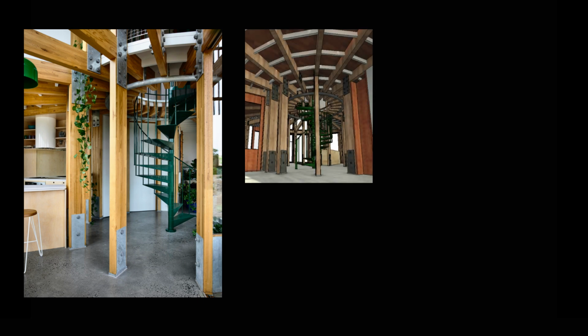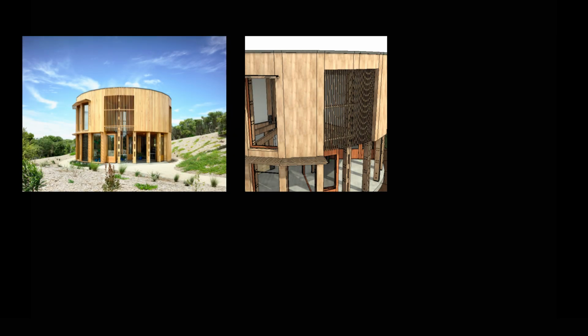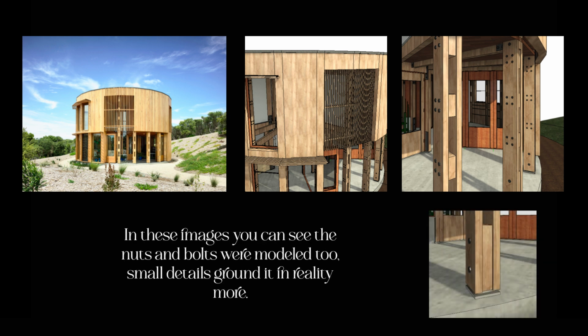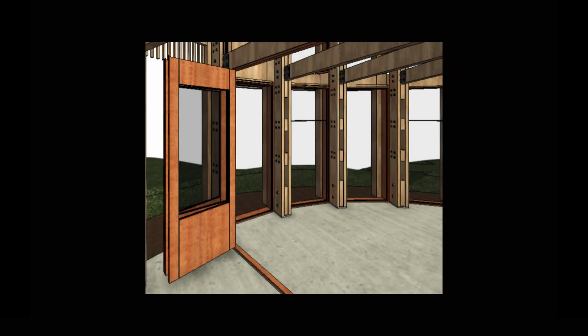You can see here that I did the extra little ceiling beams and I also did the pantry closet. And these were done by just eyeballing reference images. As for the screen and overhang, you could easily do those with Model in Place from a top-down view. And I also did these structural inserts to the columns. And there's also this little concrete footing where I cut away a small part of the foundation. As for doors and window frames, it's also just more Model in Place. For the glass, I just took a material from a Revit template.